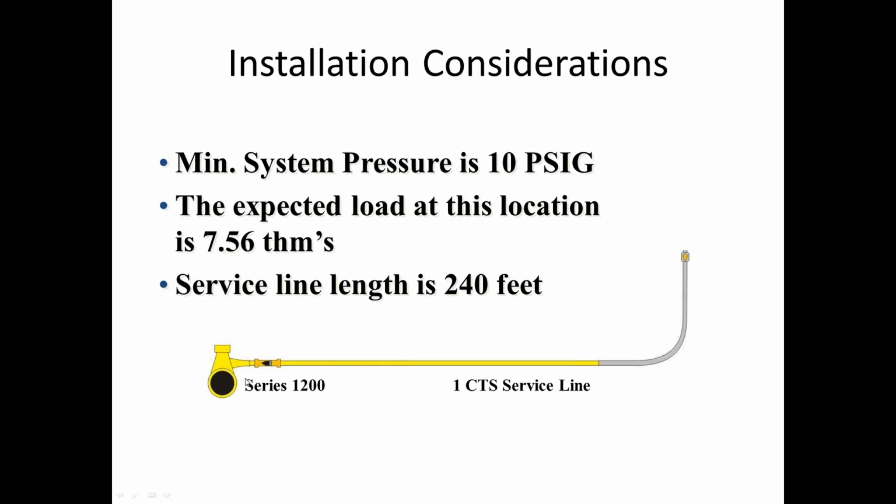But whatever it is, you just have to make sure that you have selected that series and the valve and the pipe size so that you do cover the entire length and keep the parameters that we talked about earlier, with the pressure at the regulator and the trip point above the anticipated load.